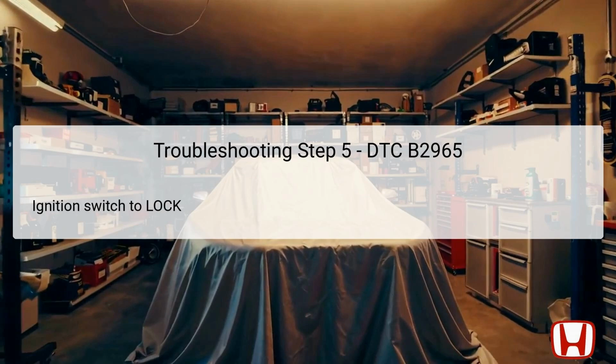In preparation for further diagnosis, the ignition switch should once again be turned to the lock position. This step is essential for the safe disconnection of any electrical components involved in the troubleshooting process, particularly before anyone attempts to access the wiring harness of the rear AC control unit. Proper safety measures always require the ignition to be off before making any electrical adjustments.